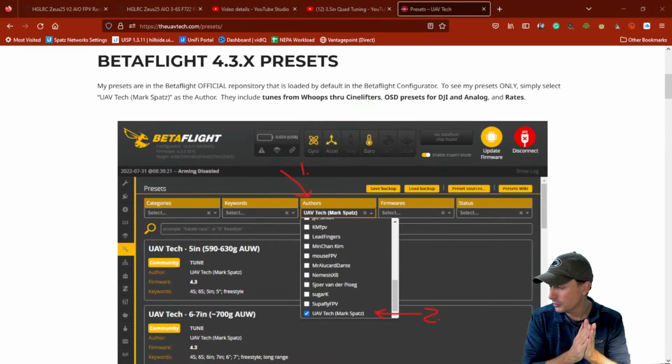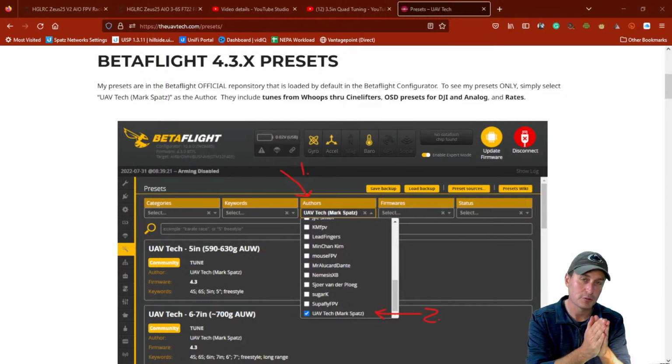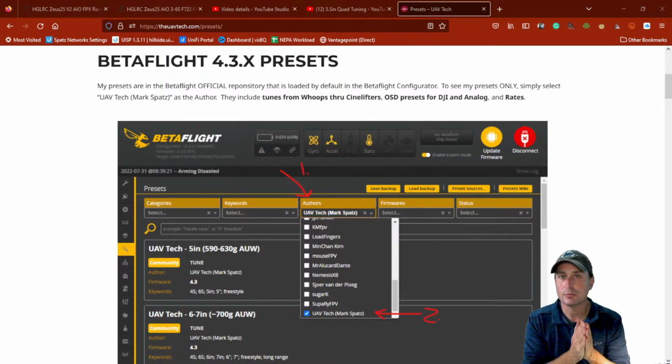So the first thing I would do is go from 96 kilohertz down to 48 kilohertz. That should give you some better low end motor torque. That may all by itself solve your wobble issue, because the 96 kilohertz PWM has kind of robbed you of that.